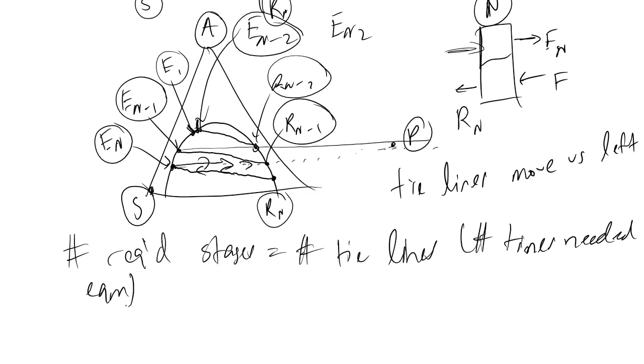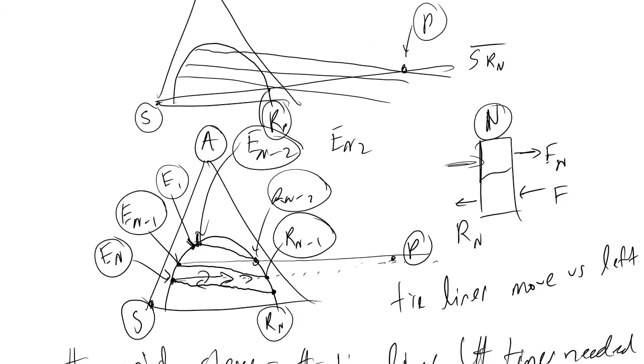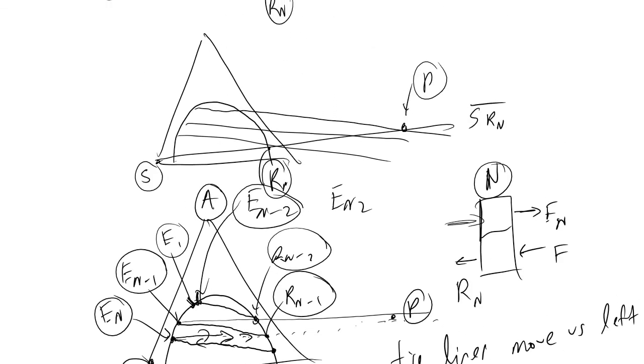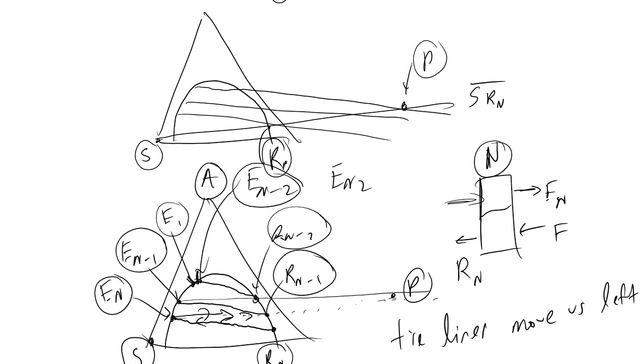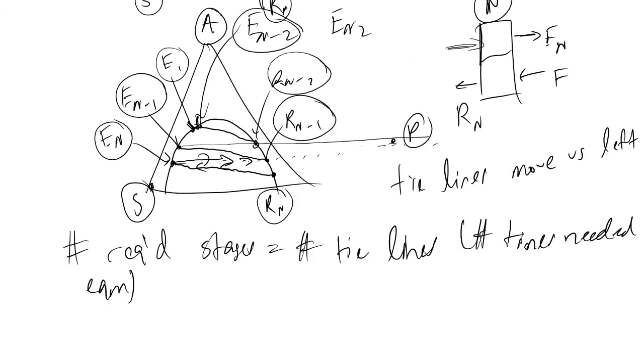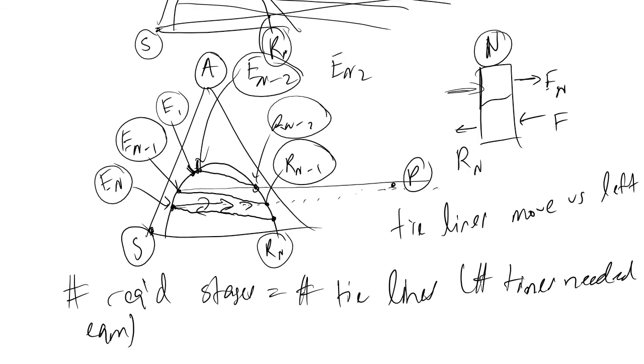And I'm sorry for being so messy with this stuff. Ternary diagrams can lead to inaccuracies, and it is very common in practice to use Aspen, but in introductory chemical engineering classes that discuss mass transfer and introduce the concepts of liquid-liquid extraction, this is how we evaluate things graphically. It's how we evaluated things before we had computers and Aspen. So being able to do this and understand the concepts involved is very important.